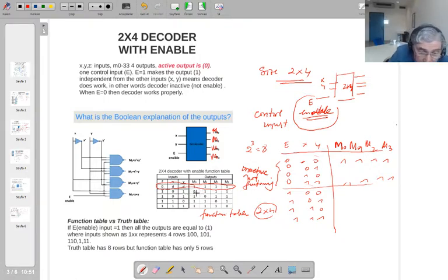If you write the second canonical form for that M0, it's going to be this, isn't it? So that means true max term, 0 is this function. Why is that? There is only one 0 value for this function. So in the second canonical form, we write the true max terms. That means sum terms. Each 0 represents one sum term.